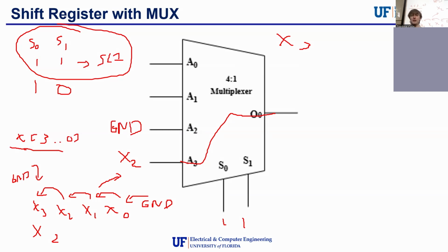And that means that we can actually have an additional functionality without needing more flip-flops. And again, the point of this whole class is how can we create something using the least? So by utilizing mux and their selectability, we can actually remove the necessity for having an external shift register.